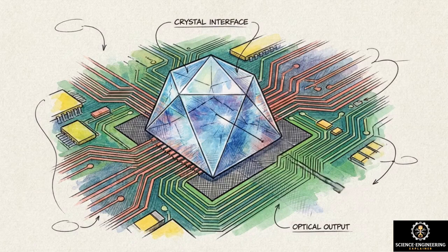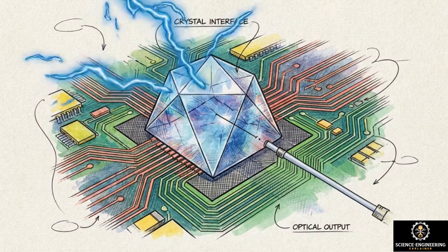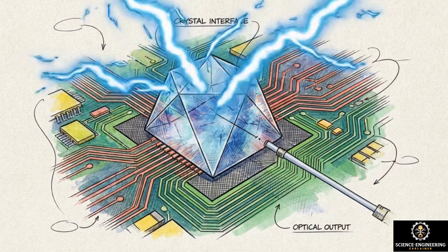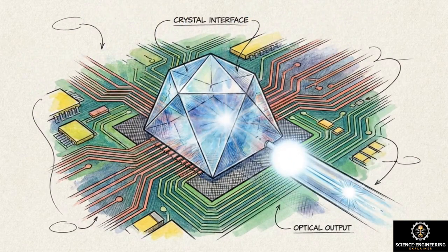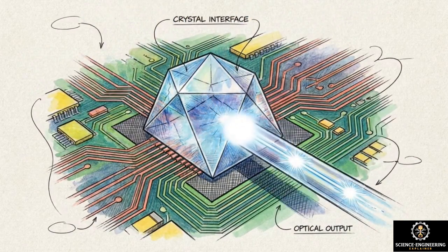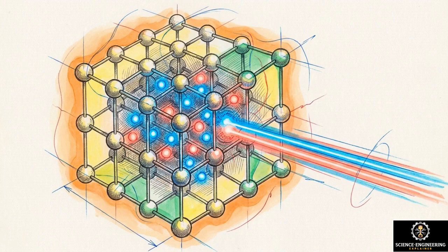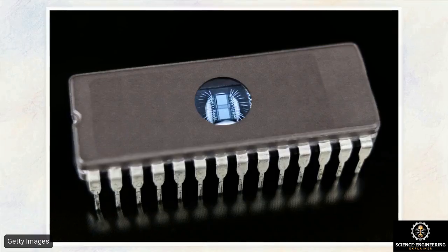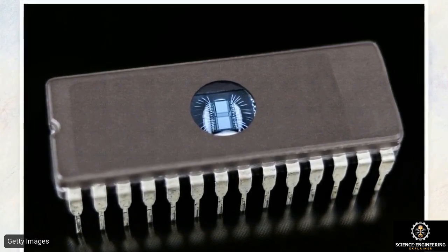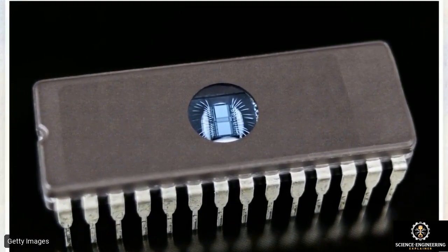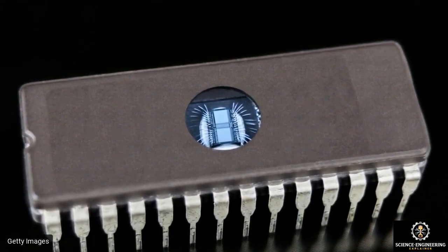For converting electrical signals to light at high speeds, thin-film lithium niobate offers electro-optic modulation bandwidths over 100 GHz at low driving voltages. For light generation and amplification, monolithic III-V quantum dots provide temperature-stable on-chip lasers. Next-generation optoelectronic integration relies on the heterogeneous assembly of optimized physical materials to process data at the speed of light.